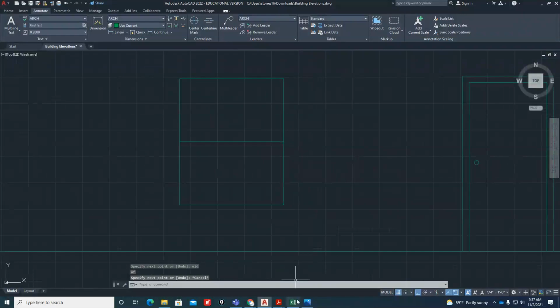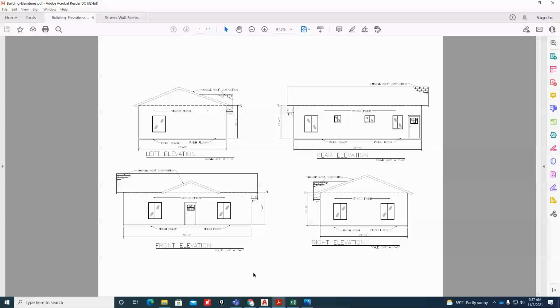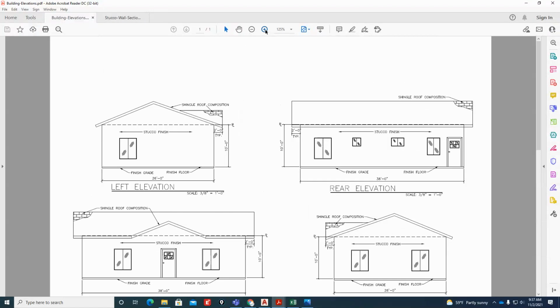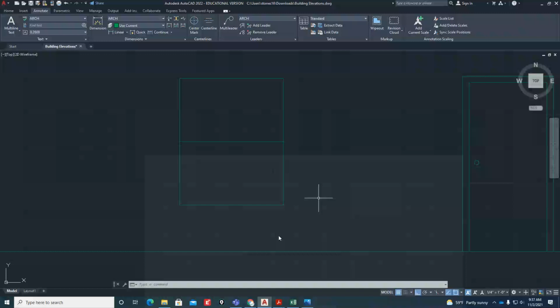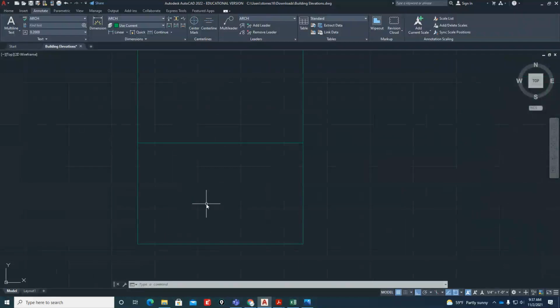So usually the representation of glass is accomplished by these little symbols that look like about a 45-degree angle. Just these little lines, like little dashes, to make it look like glass, and that's the universal representation of glass. So you put that where you want it to look like glass. So I'm going to change my layer over to the hatch layer, and then draw a line. Again, nothing really fancy about it.